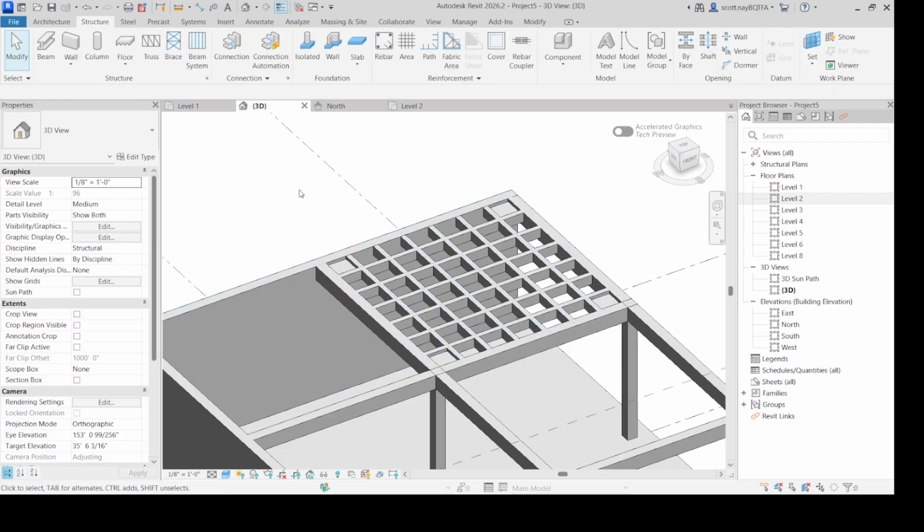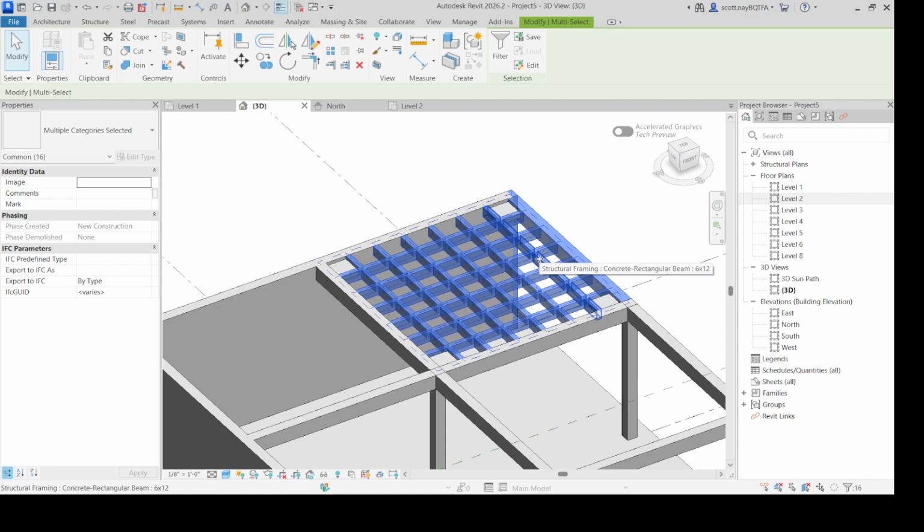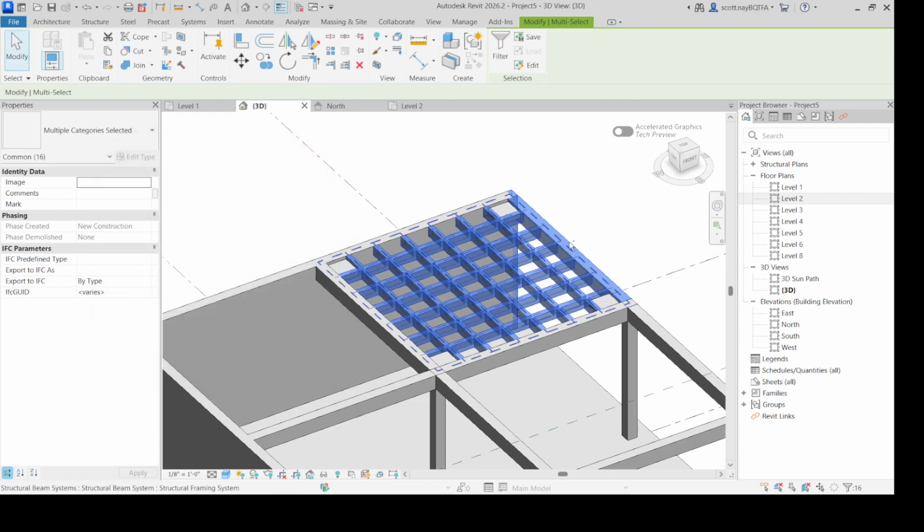All right, I'm going to try another tack here. Check my filter. Hopefully I have the floor in there. I don't. That's okay. I'll add it in a second. I'm going to hold shift and get rid of that. And then I'm going to add, by holding control, those floors.